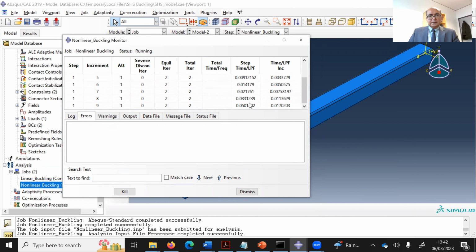The analysis is running. It is applying increments slowly, and then you can see that it moved to 0.37. It means that 0.5 times the loading, 0.6 times whatever. Now you can see that here it is undergoing some kind of deformation. So that's why you can see these U increments. And now from here, you can see the analysis is decreasing the increments, which means that now it is failing.